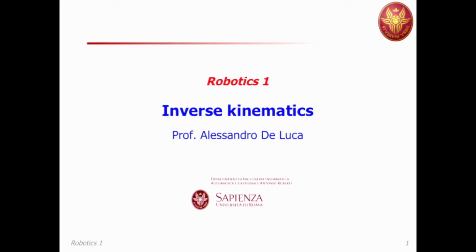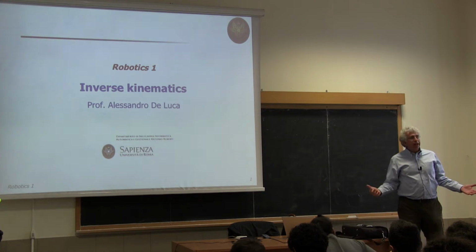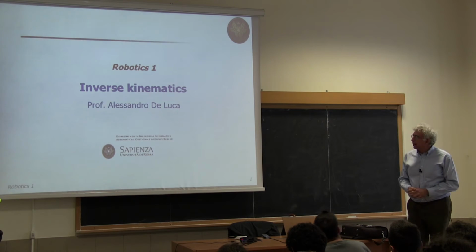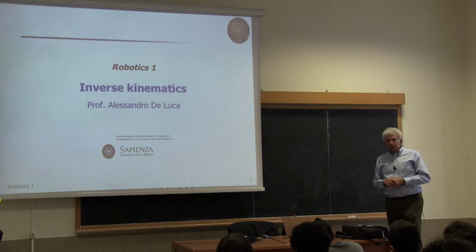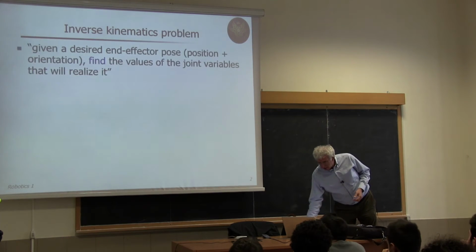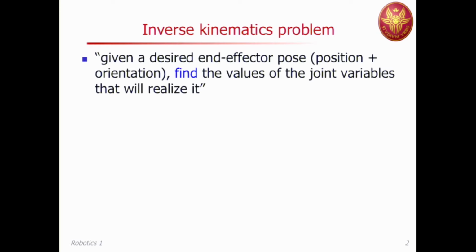Okay, so let's start again with our basic task. We have seen that we are now able to compute the direct kinematics of arbitrary manipulators, provided that they are open kinematic chains. Now we will address the inverse problem. So what is the inverse kinematic problem?